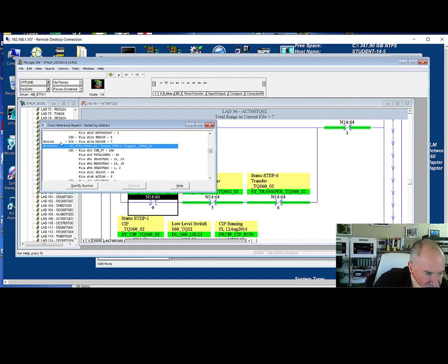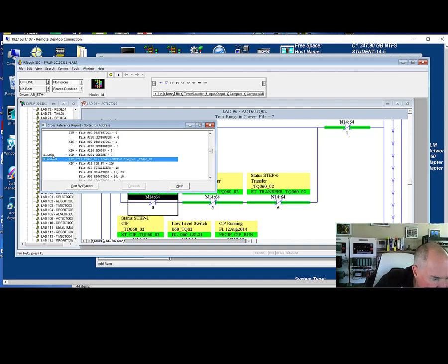And in this case, I also have these decodes, which take and change the entire word. I'm not finding an individual bit here, but I will find whole words rather, for these. So if I look to N7:64, I find the decode right here, and I'll find one of those. This is the thing that changes this.